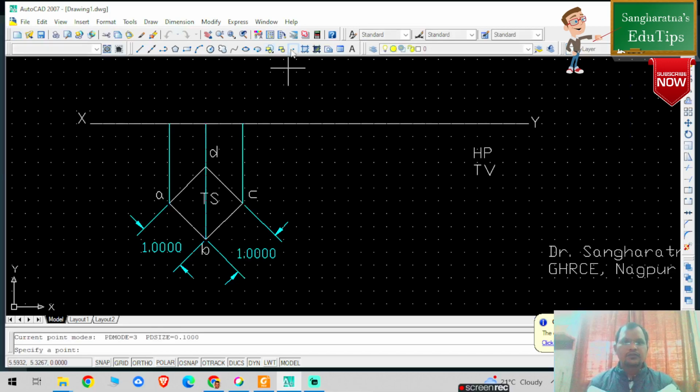Now I am going to mark the points of intersection with the XY line. This is my first point intersecting the XY line, this is my second point, this is my third point. Then I am again going to write the dtext command, selecting any point on the screen, height 0.2 and rotation angle 0. So this is my A dash, this will be my B dash and D dash, and this is my C dash. So this is basically my true length, dear students.